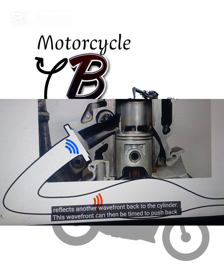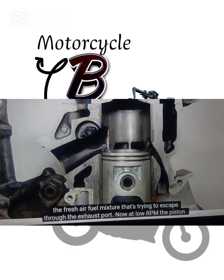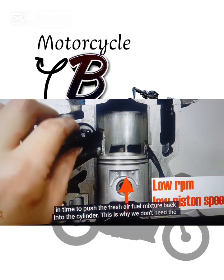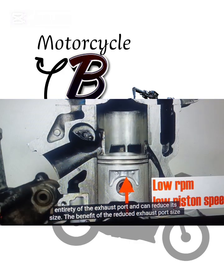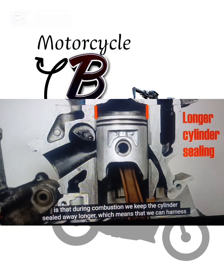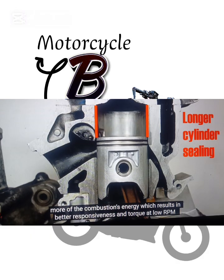This wavefront can then be timed to push back the fresh air-fuel mixture that's trying to escape through the exhaust port. Now, at low RPM, the piston is moving slowly, and this means that the reflected wave from the expansion chamber can easily make it in time to push the fresh air-fuel mixture back into the cylinder. This is why we don't need the entirety of the exhaust port and can reduce its size. The benefit of the reduced exhaust port size is that during combustion, we keep the cylinder sealed away longer, which means that we can harness more of the combustion's energy, which results in better responsiveness and torque at low RPM.